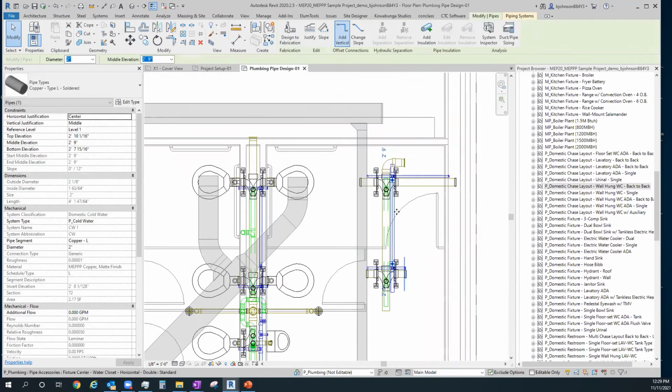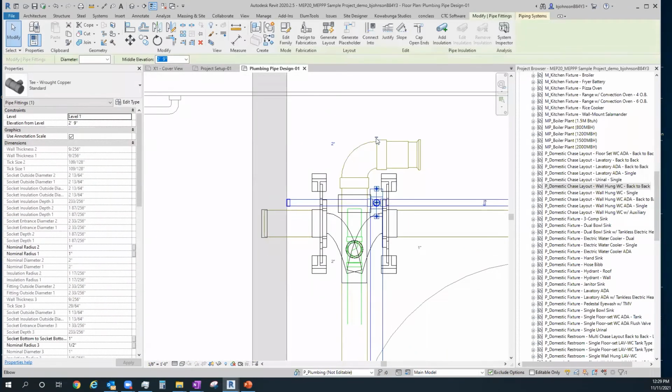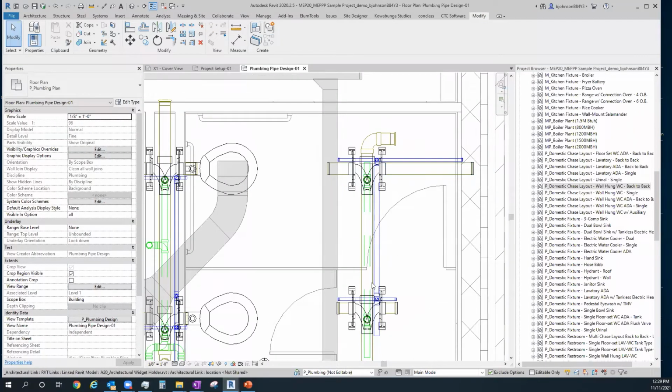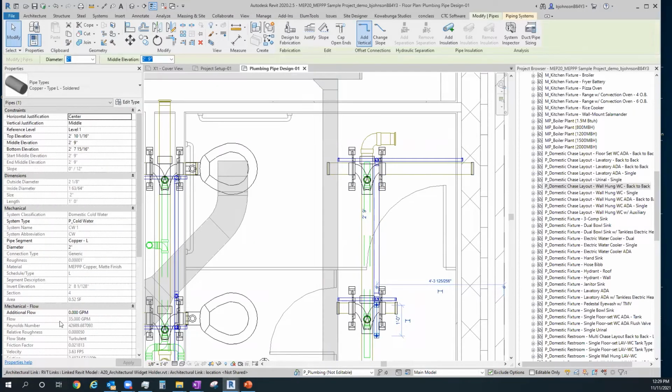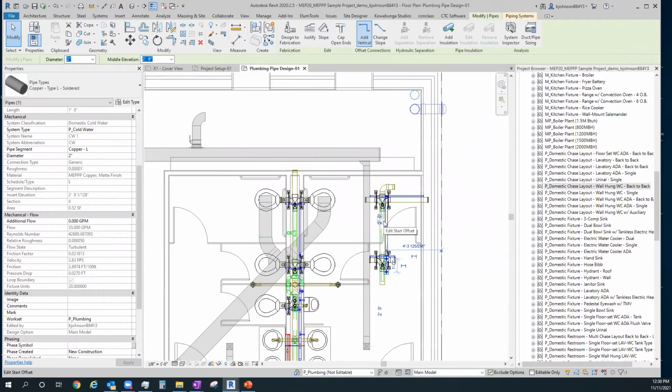And then whatever pieces and parts I don't need, such as this little extension of my water line, if it's coming from the opposite end, pick on that, grab my fitting till there's no longer a T, it's just an elbow. I'm collecting fixture units on that pipe the whole way. So I come down here and select on that. That's my 20 fixture units, because each water closet is 5. So if I'm collecting fixture units on that, then I can also run pipe sizing routines and get that to size itself automatically as well. Literally, I can do a chase in 10, 15, 20 minutes, depending on how many fixtures I've got actually connected on that run. Makes things super duper fast, really, really easy.